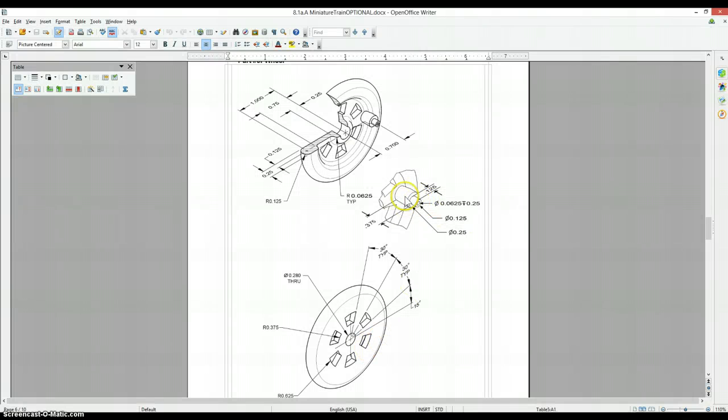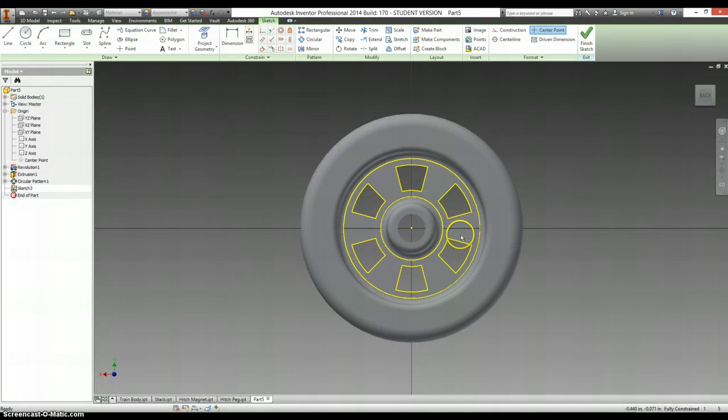There's a little part that's going to connect to the axle, and it looks like, where's the diameter of this? Here it is, 0.25 diameter, and it's located over 0.7. So 0.25 is the diameter, the distance over we set is 0.7.